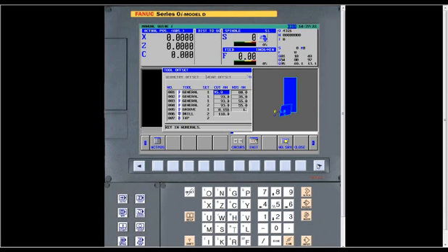So if it was perfectly square, it would be 90. So you take 90 and add the 5 degrees of clearance, and that's where you get to 95. Then the nose angle is the actual shape of the insert. Not the clearance relief on the backside, but the actual shape of the insert.